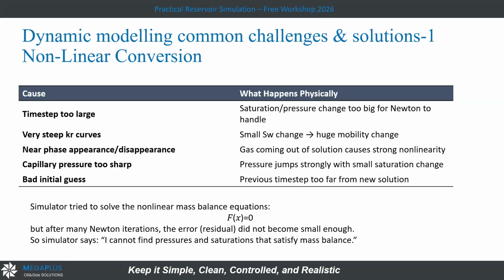Imagine you have a time step that you want the simulator to use to calculate what happened in the cell, and you make the time step too large, so a sudden change in the cell will happen. That's a bottom line in reservoir simulation. You have to be smooth in geology, smooth in the time steps, smooth in everything. So you don't have to make it aggressive, like yesterday I told you, transmissibility shock or permeability shock. Never. The model must be smooth, with no sudden, very big change.